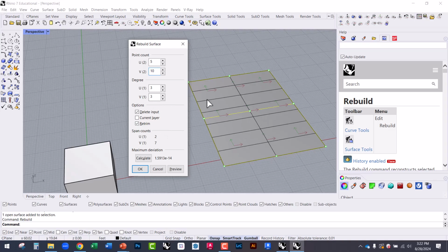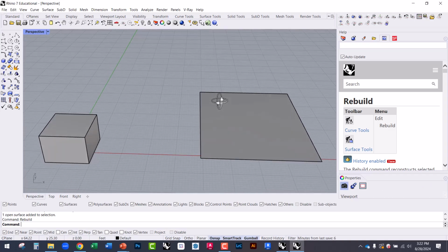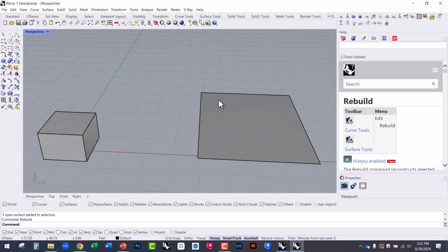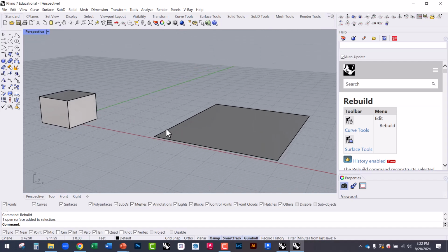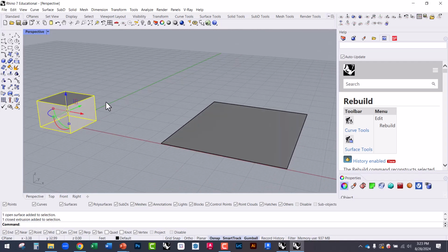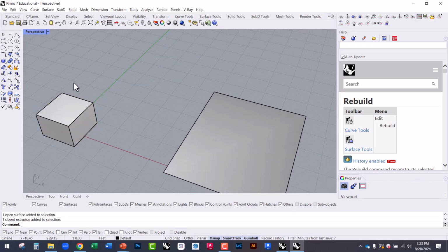Okay, so anyway, I don't want to get too deep into that, but I just want you to know there's two different coordinate systems, one an X, Y, and Z for the whole Rhino world, and then there's a U, V, W coordinate system for surfaces. Okay. All right, so right now I have two things in my model space. I have a solid object, which the other term for solid objects is called a polysurface, or a BREP, B-R-E-P. So that's what this is.